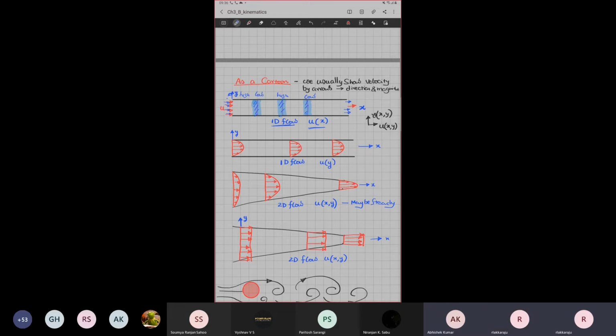So if you are thinking of something like your automobile exhaust gases coming out of the silencer, well, before the silencer, if I am really thinking of the system, this pipe just before the silencer, the pipe dimensions are so narrow or so small compared to the muffler or the silencer or compared to the atmosphere, the entire flow comes from one location to another location, acts like one-dimensional flow compared to the flow which enters the muffler or the silencer. Because at the silencer there is so much porous kind of media, whatever flow comes is starting splitting, goes in upward direction, downward direction.